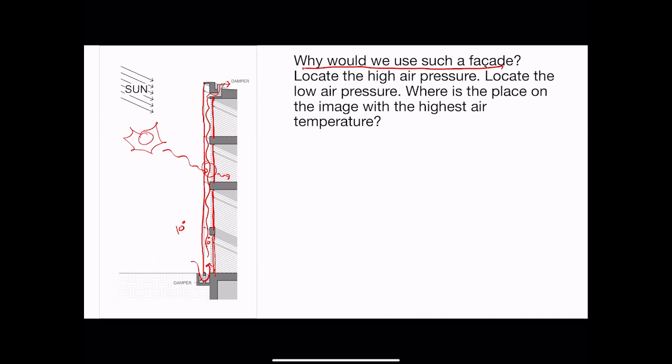the damper. Now, the reasons we typically use a fan are, well, we can't always trust that the sun's going to be out and it's going to be hot enough to have enough pressure to really push that damper open, as we saw with my bathroom fan. But also because sometimes the wind is blowing this way, and then that blows the damper shut. And even if it doesn't blow the damper shut, let's say there was just a grill there or something like that, it still would blow the air back.